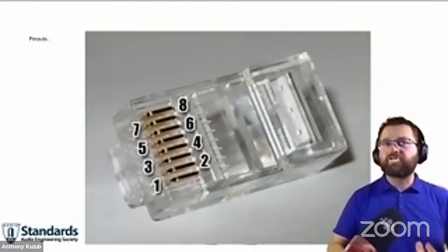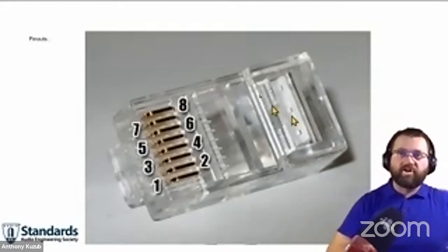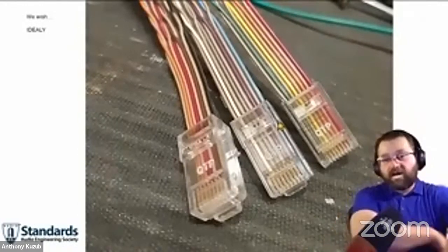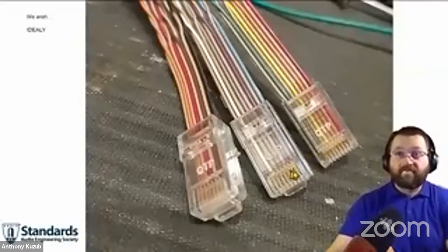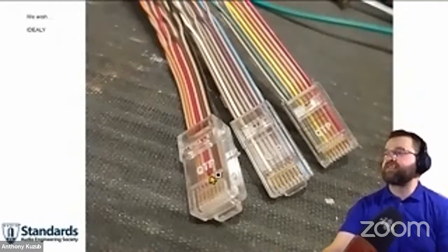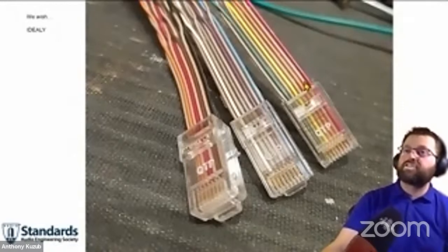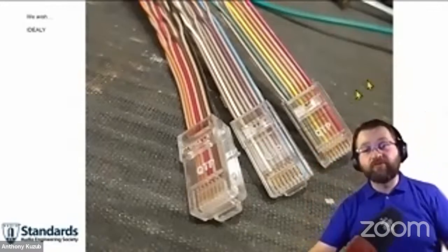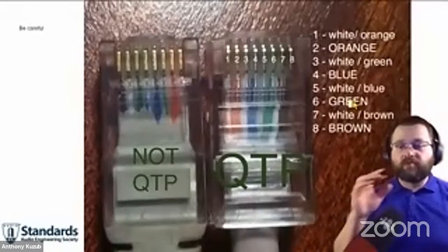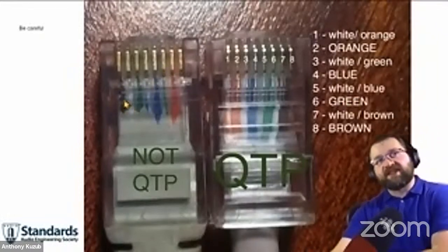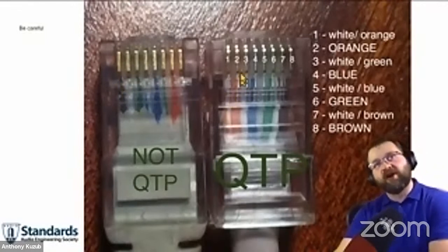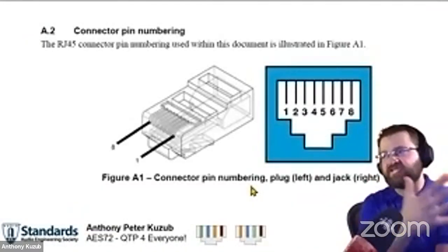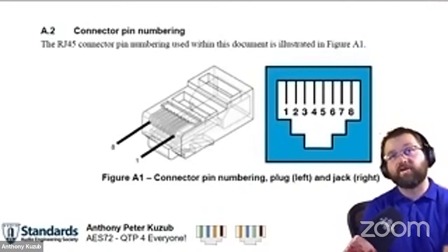Like I said, you look at this very simple, unassuming connector, and this isn't even the best of the bunch because this isn't a shielded version, but it's pins 1, 2, 3, 4, 5, 6, 7, 8. In an ideal world, the colors would go red, orange, yellow, green, blue, violet, gray, white, black, red, brown, and it would repeat. But we didn't luck out. We got this industry that's full of nefarious cables that have solids on pin 1 in one version, and solids on pin 2, and we've got these standards that we have to adopt. So we set out and said, okay, look, this is pin 1 when you look at it.